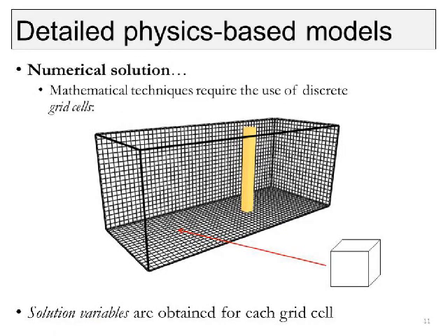And one last thing about the details of the modeling approach. I think it's important going forward with this talk just to understand some of what I'm talking about, to understand that in order to actually solve the mathematics of the model, to get an answer, we have to divide our computational domain into this grid, this numerical grid, where we have all of these discrete grid cells. And then for each grid cell, we're getting a variable such as the temperature or the velocity of that flow or the density and so on. And then we can piece all of this together to get a three-dimensional representation of what's going on. So just keep in mind these discrete volumes that we're dealing with as we move forward.